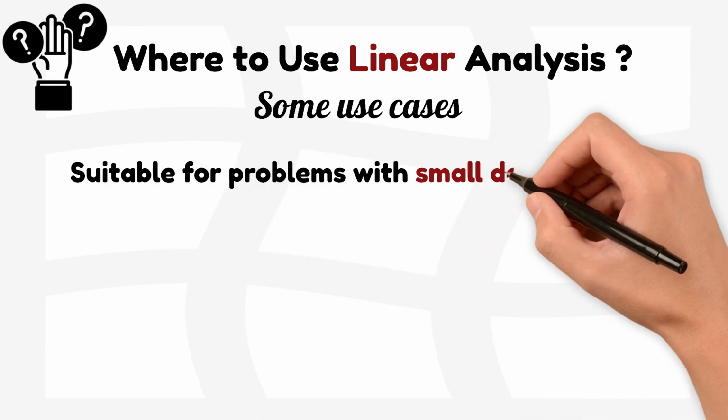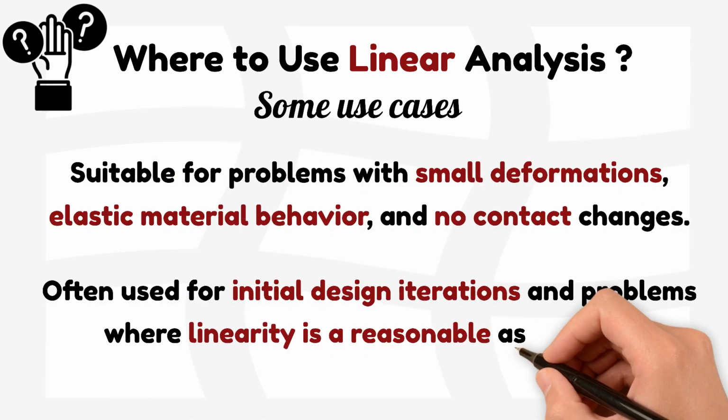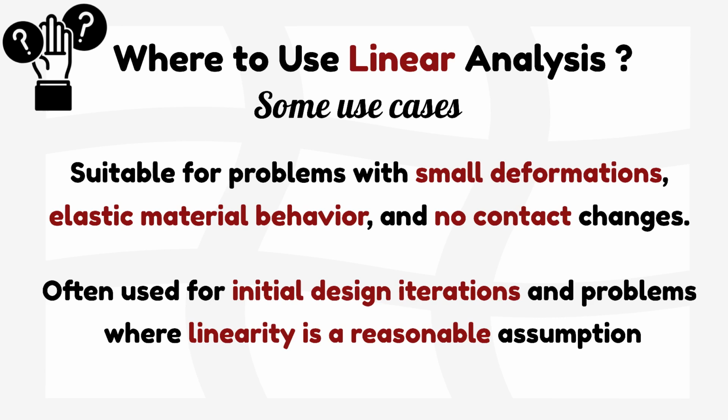each one. Starting with the linear analysis, it's best suited for problems involving small deformations, elastic material behavior, and no contact changes. You'll often use it during early design stages or whenever linearity is a fair assumption and you just need quick and reliable insights.